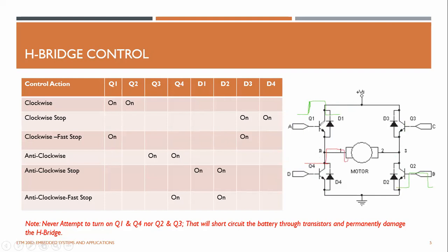So you have to start at the point that this guy turned off, right? But do not keep this turn on period beyond this point, because there's a time period where both transistors are turned on. So in order to avoid that, we can have some kind of dead time.